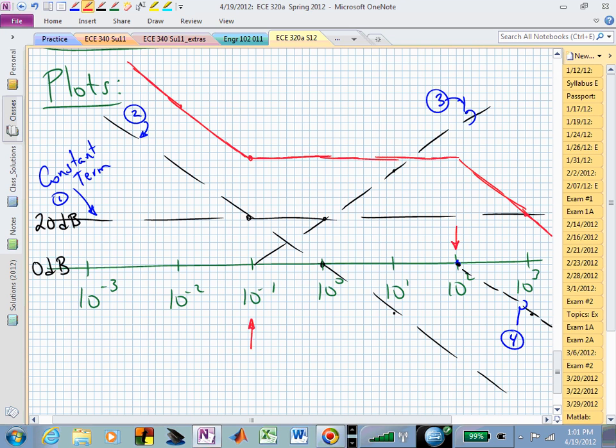What's the gain in absolute terms at omega equal to 1,000? Or, okay, what is the gain in dB? 20 dB. So converting that to absolute, you have 20 log x is equal to 20. So log of something is 1, 10. So you have a gain of 10 at this frequency, and you had a gain of 100 at this. Remember, this is a dB scale. So this linear distance means quite a bit of change in terms of absolute value of your gain.